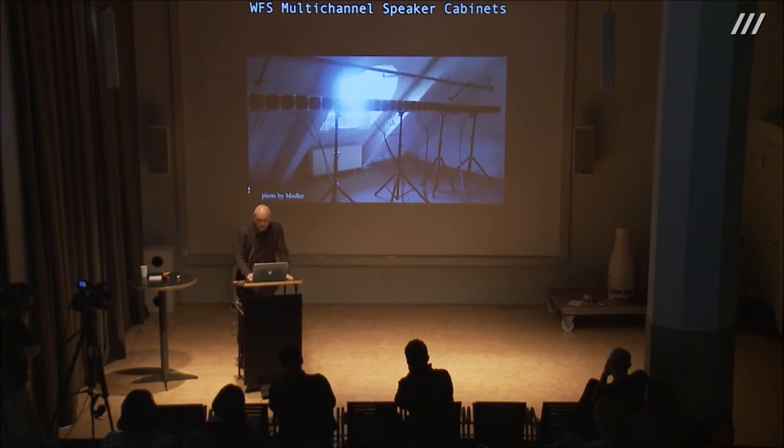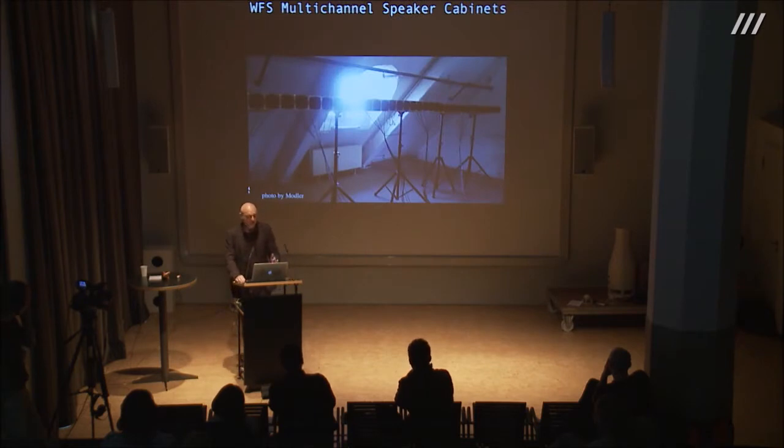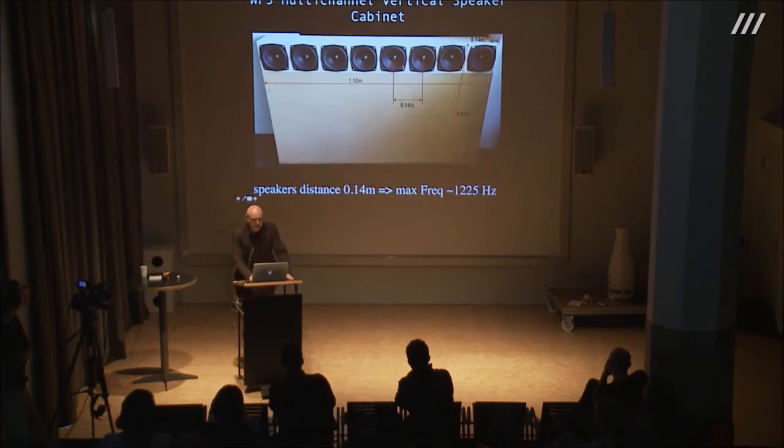And first we built 2 of them to test whether it's in some way working. And then very fast in, as you see, some spaces hidden, some special rooms, and have some tests. The boxes provide a distance of 14 centimeters between the speakers, which gives a maximum frequency for wavefield synthesis of about 1200 hertz.